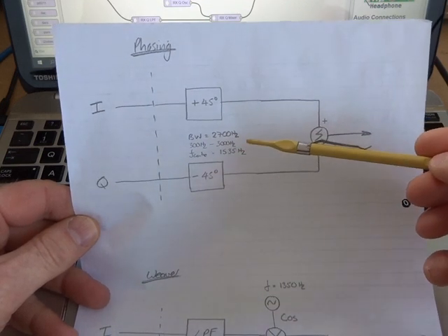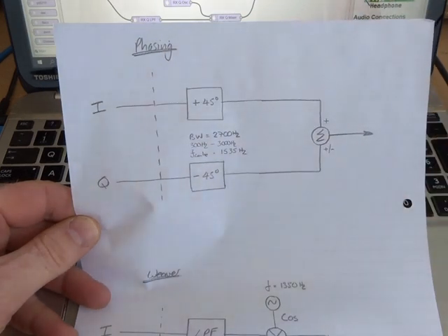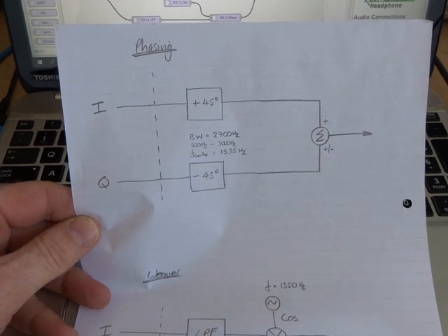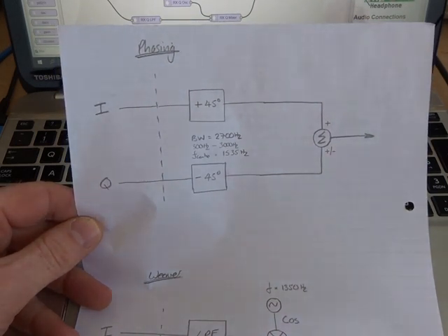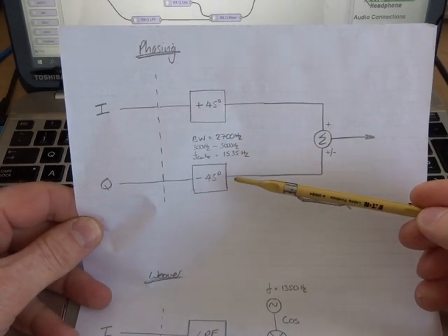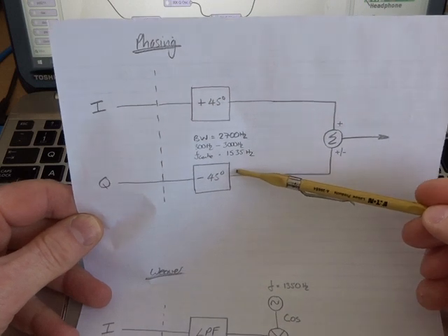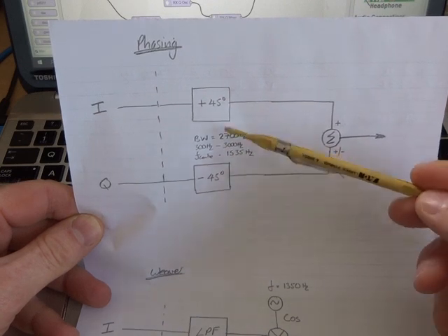In this particular case, for these Hilbert transforms, I used the Iowa Hills software, which we'll have a look at in a sec. That's free software you can download from Iowa Hills to generate the coefficients that will fit into the two FIR filters within the Teensy.